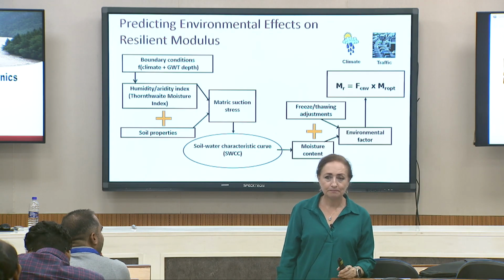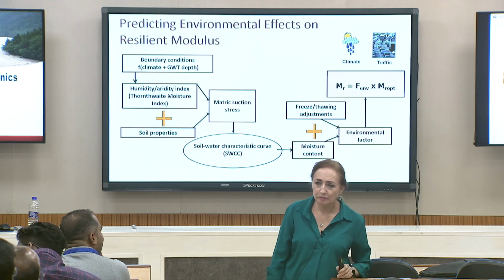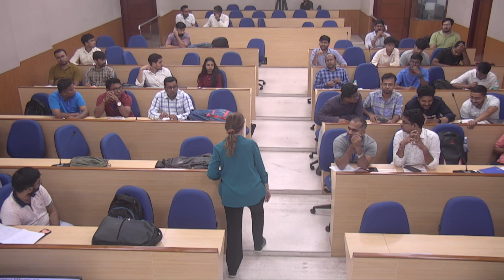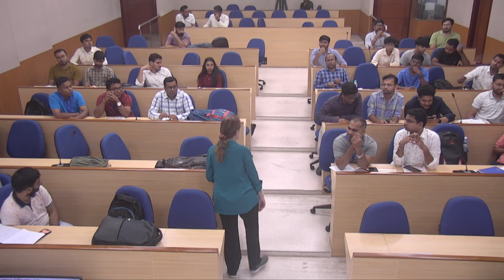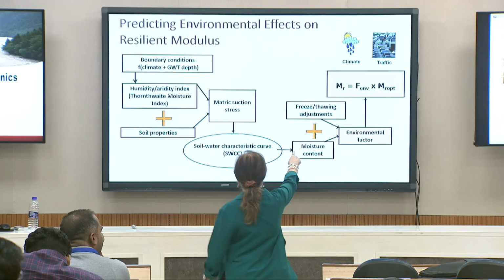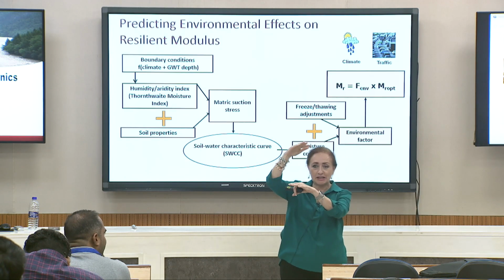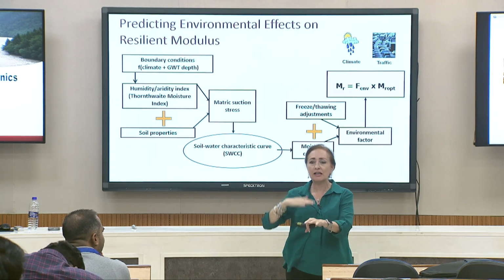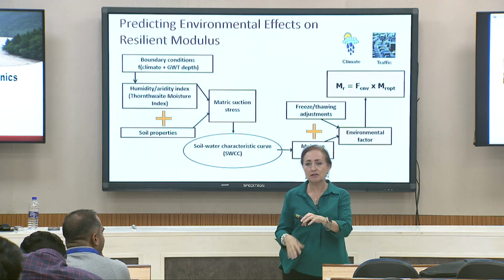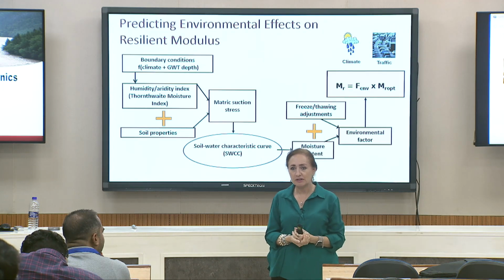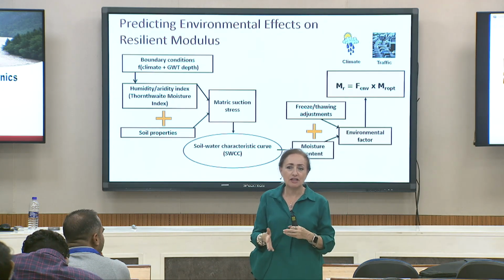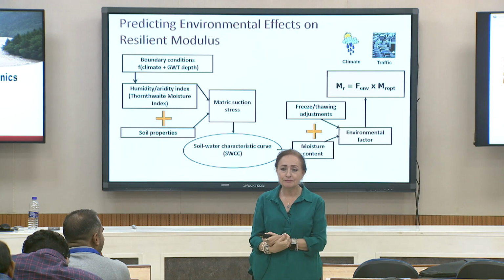Okay. As an input, I think we have to give a trial modulus for each of the layers on the design modulus. Yes. So this resilient modulus at optimum is done for the granular base material, for the subgrade material, and for the subbase and subgrade material. So you get that one. And all of them are going to have the stress conditions that are in the field.